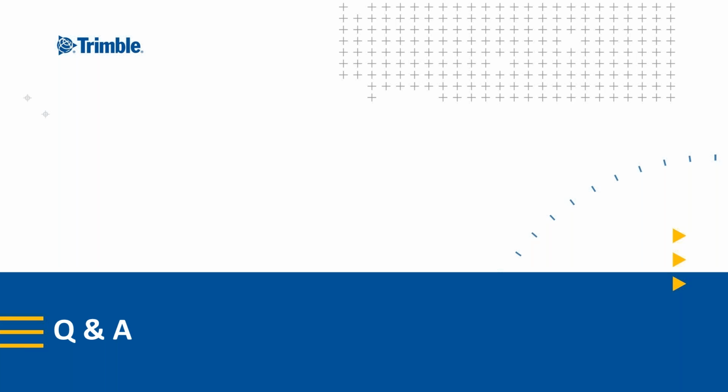All right, and then there's a question: for orientation, do I have to select GNSS IMU? You do not. If you do not select that when doing the tie point extraction or for orientation, it just will not use those weights. If you have good information, it is a good idea to use that, and it'll constrain the products that you're creating and the matches to the actual location of those images instead of only using ground control points. If you have poor GNSS and IMU data, then don't use it. If you have high accuracy GNSS and IMU data for the image locations, then yes, use it.